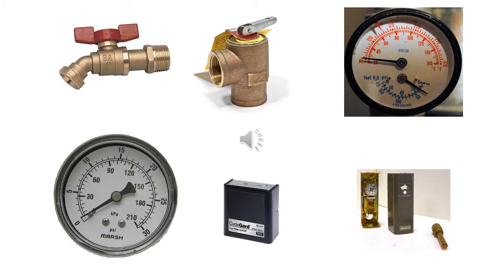The temperature and pressure gauge is designed to show the temperature and pressure of the forced hot water system. The picture on the upper right is of a tridicator gauge. The red colored arrow indicates the normal range that the boiler should operate at. The picture on the lower left is of a pressure gauge. On a steam boiler, there is only a pressure gauge.